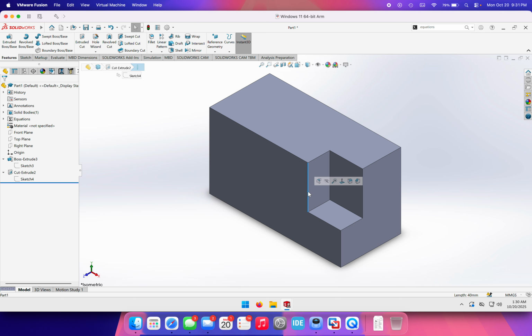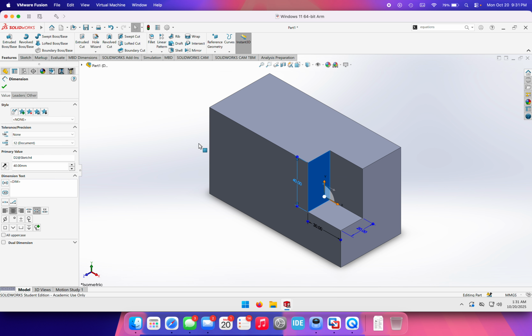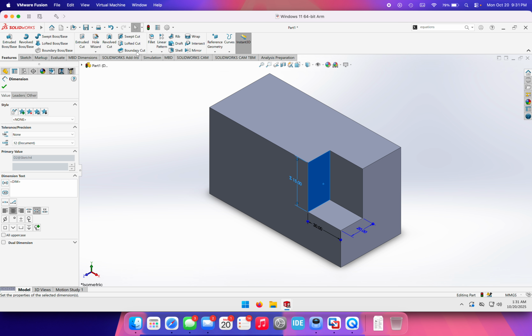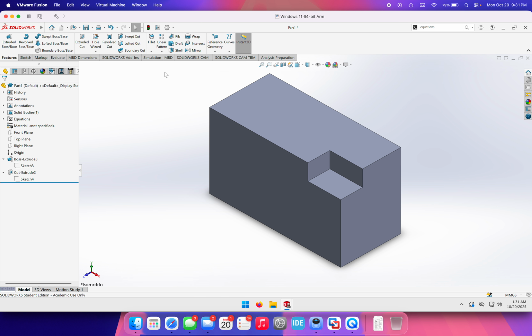So that means there's a sort of 1 to 3 ratio going on, but I've set this height as a fixed 40. So what I can do is double click on it, press backspace, select global variables, and select our cutout height. And that's going to change it to 15, because that's what it is set to under the equations and variables folder.